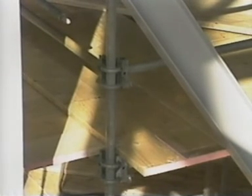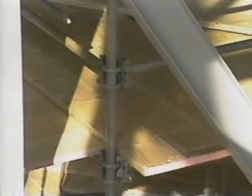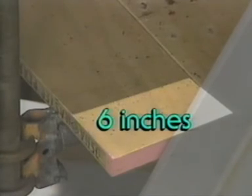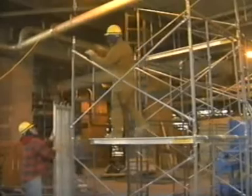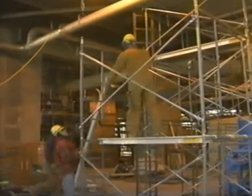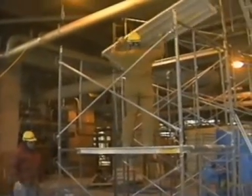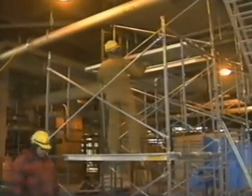If the planks are allowed to extend beyond the 12-inch maximum, there is a risk of dislocating a plank by stepping on the unsupported end. The minimum 6-inch extension is necessary to assure that the planking does not slip out of its supports under pressure. Some prefabricated scaffolding uses metal planks attached directly to the support rails. In this case, the platform need not extend beyond the support points.